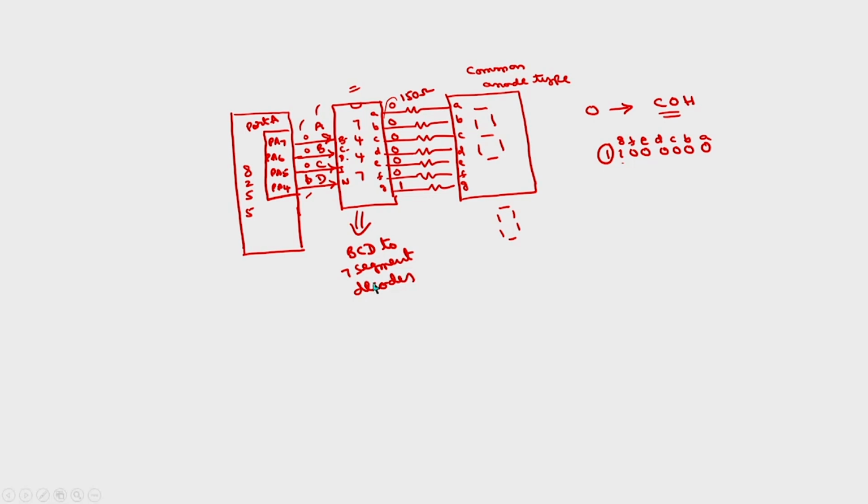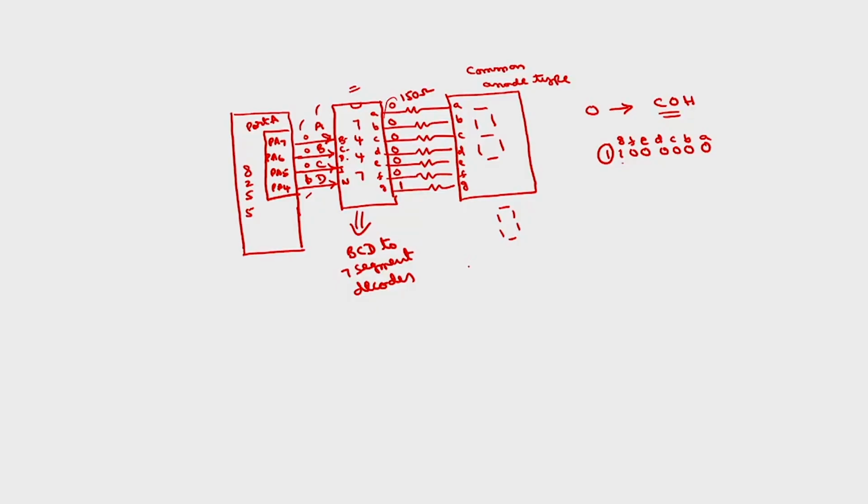So, the job of the BCD to 7 segment decoder is, as the name implies, you give the input as BCD, output is 7 segment display code. Depending upon whether BCD is 0, 0 code will be generated, 1 code will be generated, and so on. Now, how to write the program? Again, to implement the same decimal counter or mod 10 counter.